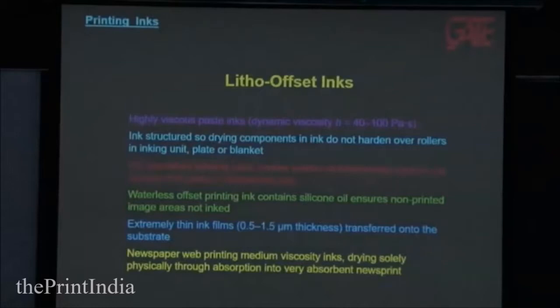So now litho offset inks. These are highly viscous inks, and these are paste inks, consistency like toothpaste. Dynamic viscosity 4200 pascals. Ink is structured so drying components in ink do not harden over the rollers. So you don't want your ink to harden on the rollers. It must dry on the substrate or in inking unit or plate or blanket.